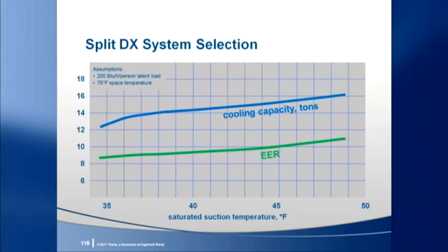If the coil is selected at low suction, then hot gas bypass will be required to operate sooner to try to stabilize the coil temperature. Remembering that hot gas bypass is not an efficient way to unload, it's easy to see that a system selected at higher suctions that doesn't so quickly need hot gas bypass to operate will use less energy.